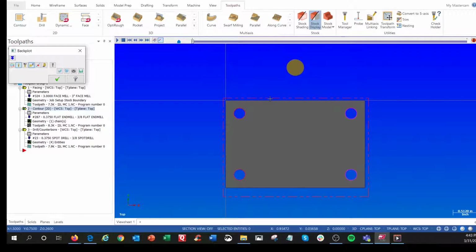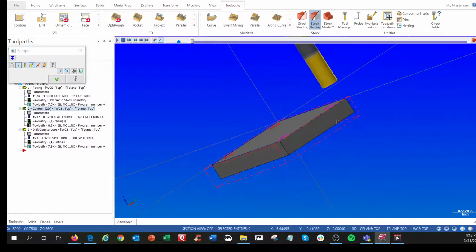Let's say that this is the Y0. So if it was up here and say it's Y positive 1, that's clear. And halfway, that would be X 1.5, because this would be 3 inches. All right, so it's going to position, spinning the RPM that I figured out. It should spin in the clockwise direction. I'm going to engage the tool height offset, bring that down. Then we're going to feed down to the bottom of where this is, and maybe a little bit extra, like 10 thousandths.